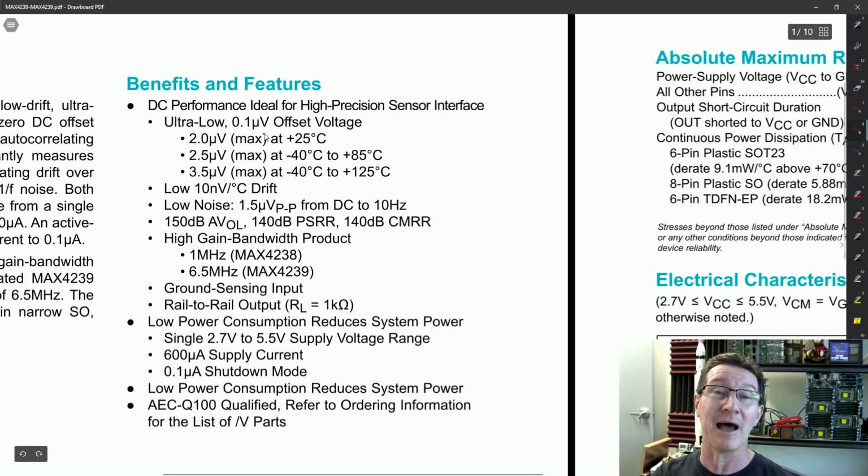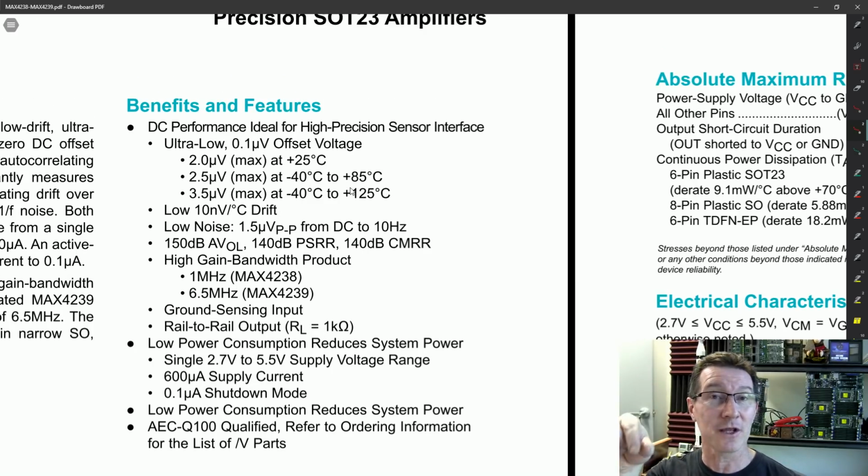You can actually buy the parts, build up a custom test jig, measure them and then bin them good or bad. And you can do that at the component level or on the board level, because I designed a little amplifier board once that was used in a Sonoboy, and we actually designed this huge, table-size automated tester, because we were manufacturing a couple of 100,000 of these boards and we had to guarantee the performance of each one, fully characterize them with dynamic signal analyzers, measuring all sorts of parameters.